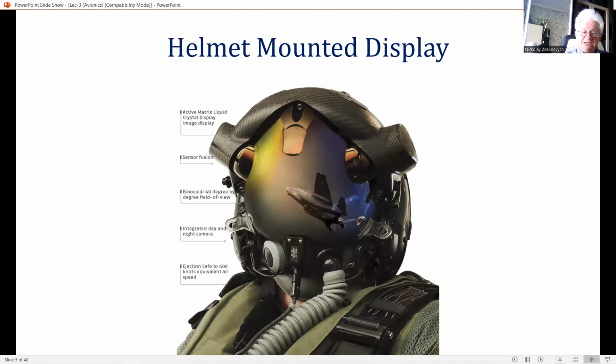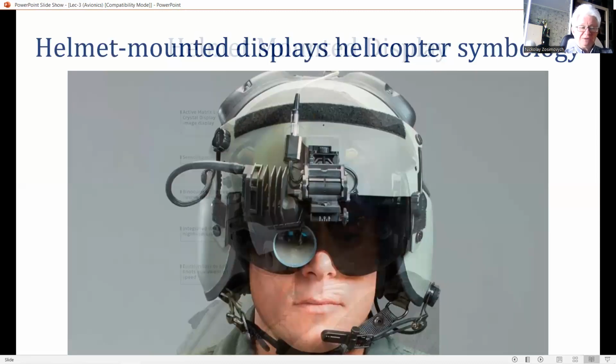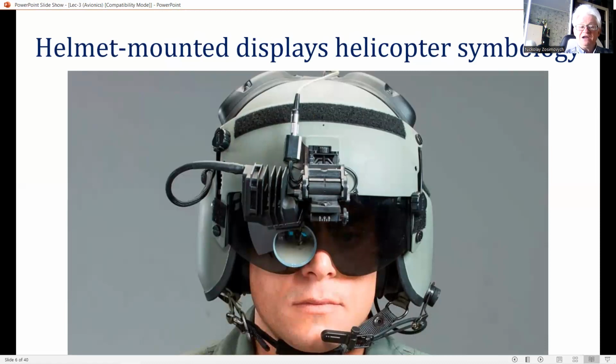It should be appreciated that the FOV moves with the head, unlike the HUD, and the larger FOV reduces scanning head movement in an HMD. It is still very useful, however, to allow peripheral information to enter the eyes so that the FOV is not just that of the optics. The HMD also enables a very effective night or poor visibility viewing system to be achieved